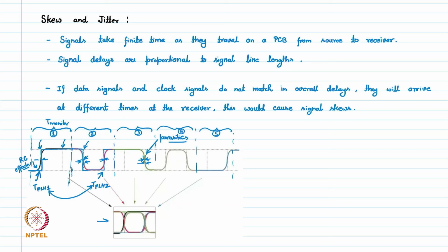This is our black curve from the first frame. Then we have this red going down. This is from the second frame, this red goes down here. This green is from the third one, and so on. So when we superimpose all these frames together, we get this type of waveform. We call it the jitter waveform or the eye diagram sometimes.